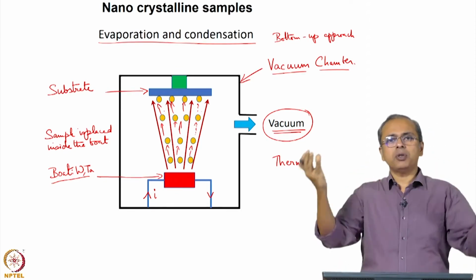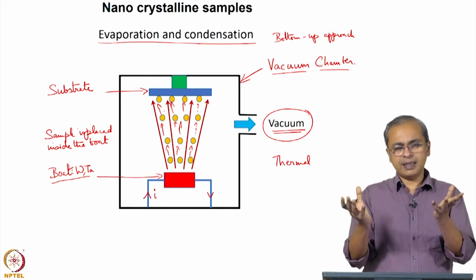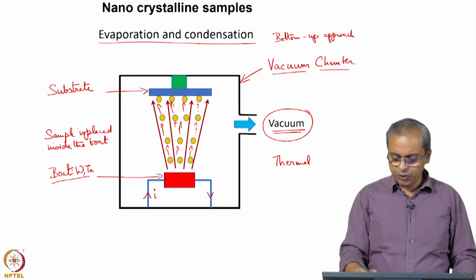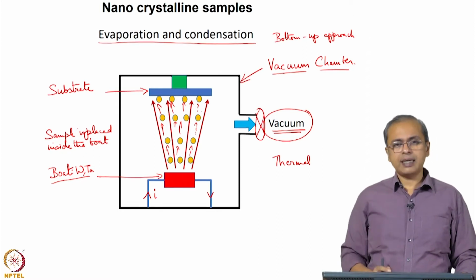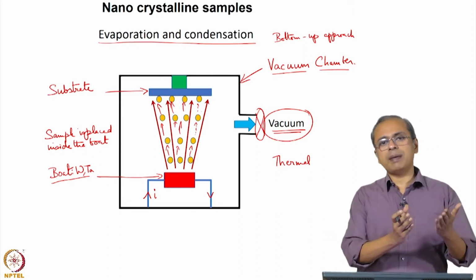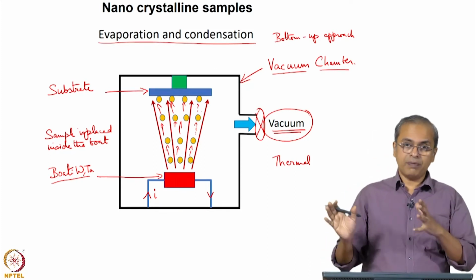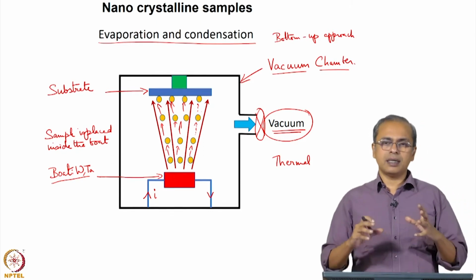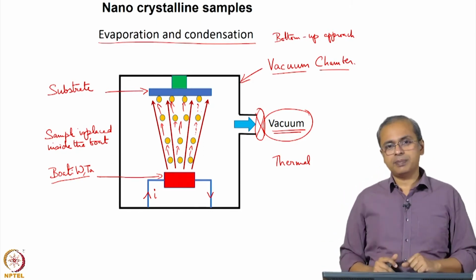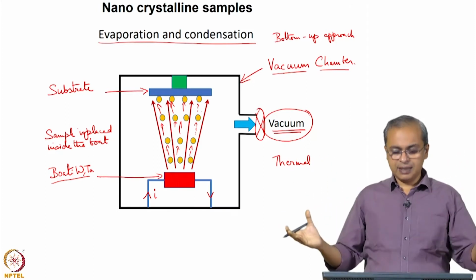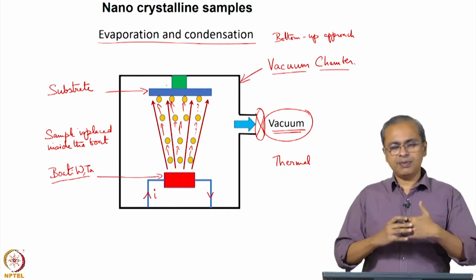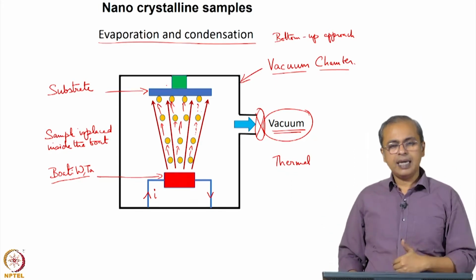So, they actually evaporate and sort of fill the chamber. Okay. So, it is like you are creating an atmosphere in there where you fill the chamber. Of course, what you normally do is after you draw vacuum, you close a valve here. Otherwise, if you keep drawing vacuum, then whatever you evaporate will also go off into the vacuum pump. So, you draw vacuum for some time, and then once you have reached a very low vacuum condition, you just close the valve there, and then now you evaporate this material. This evaporated material starts filling the chamber, and it will also go towards this substrate. So, at that point there is no specific direction in which it is headed, it is just headed up in different directions and it hits the substrate.